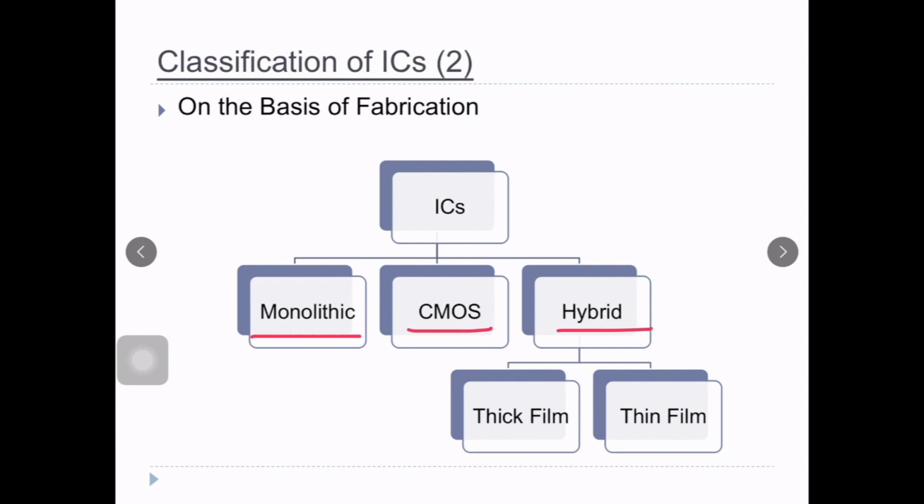The electrical isolation between the components in monolithic ICs can be achieved by many techniques, for the components placed on the substrate. When a whole circuit is formed on a single chip, that makes it low cost and makes mass production of those ICs possible. The monolithic ICs exhibit good thermal stability because all the components are integrated on the same chip, very close to each other.